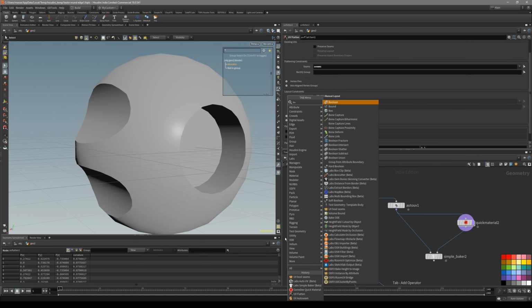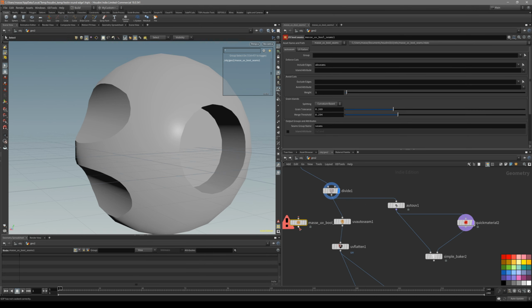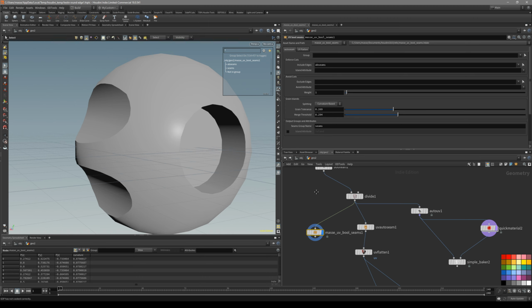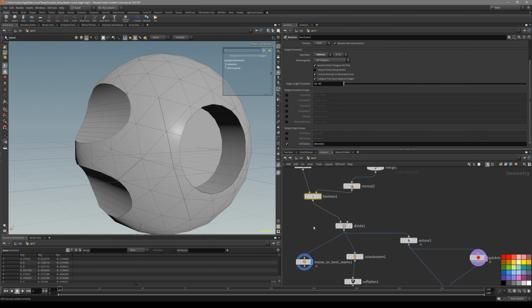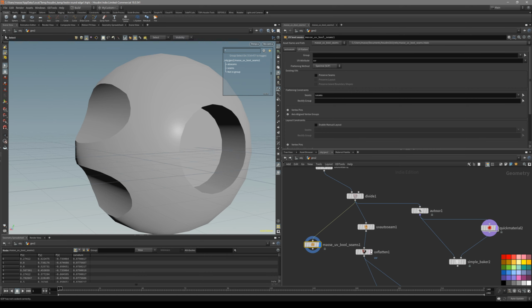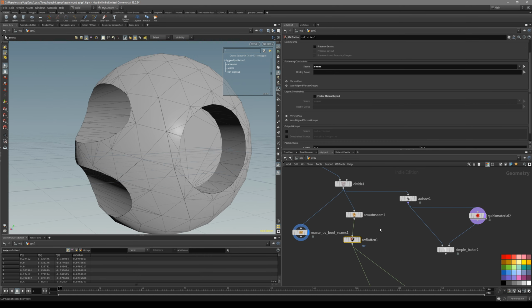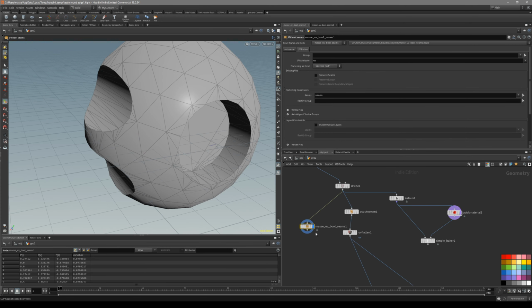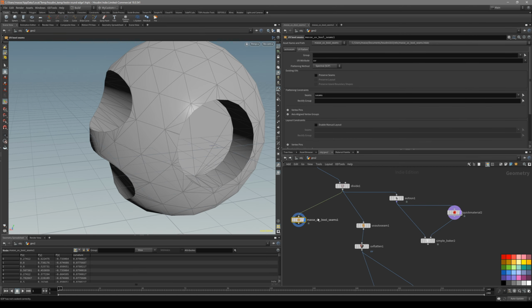Basically I provide a boolean, UV boolean seam, and before that, after I have divided, I connect inside here, and it's automatically set up for me to include the AB seams, because I know in boolean I have AB seams and UV flatten. And basically, I have the same options from these two nodes inside here. I can switch between the nodes, and without cluttering up my network with two nodes, I can get all of the options that I need from one HDA.